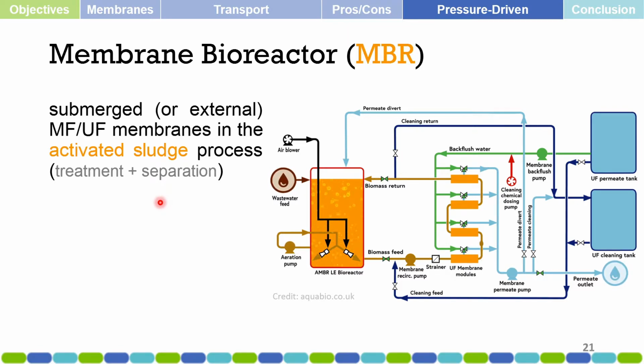So if you need a biological wastewater treatment facility and you don't have a lot of area for your plant to build secondary or primary clarifiers, then you may think of a membrane bioreactor, since it can be used for a smaller area. It has a smaller footprint for a plant design. Also, since the organic biomass is returned into the membrane bioreactor, there is a higher concentration of biomass, and thus the water quality that comes out is mostly much better than the typical biological wastewater treatment process using activated sludge.